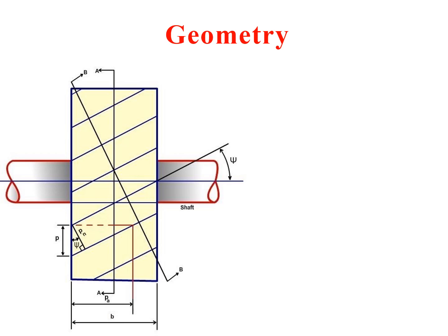Basically here you can see the inclination of the teeth of the helical gear. It is towards the left side. You can call it inclination, or slope. It is towards the left side. Or also you can say that the inclination of these teeth can be represented by the left hand thumb. So this gear is nothing but a left-handed helical gear.